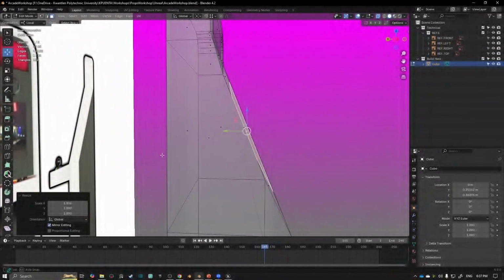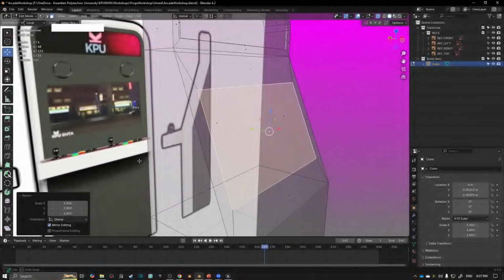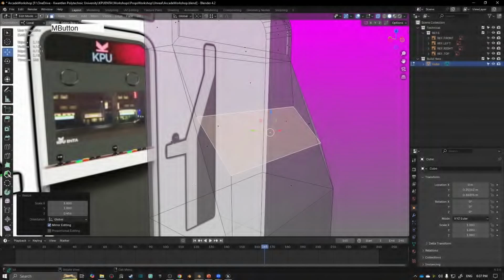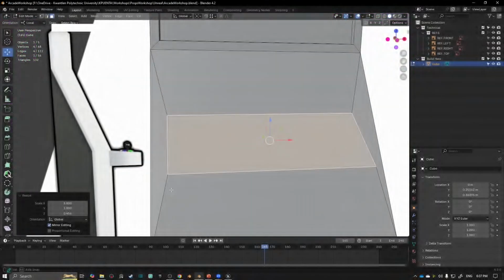Now, this one's going to be a bit weird. I want you to go all the way. It's more important to hit the height than it is to hit the width. So I'm just going to go a little bit further, like so, and then hit SX to scale out in the X. Now, the reason for that is this is on a slope, and if we were to scale in Z by world coordinate, then some funky things happen.